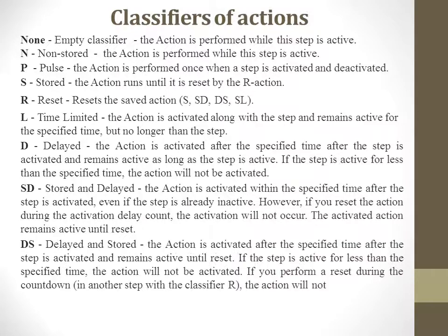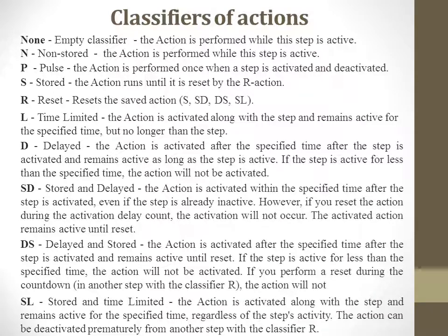So next classifier is DS. It means delayed and stored. The action is activated after the specified time after the step is activated and remains active until reset. So next, SL, stored and time limited.